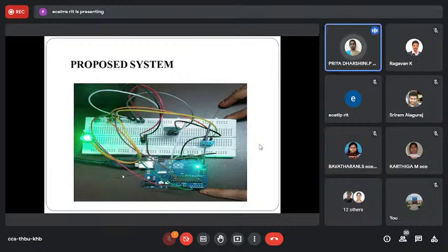The proposed system consists of an Arduino UNO, being an interface for all the sensors: LM35, DHT11 and heart rate sensor, and the HC05 Bluetooth module. The Arduino UNO is a microcontroller based on the ATmega328, and it consists of 6 analog pins from A0 to A5 and 14 digital pins from D0 to D13. This being the interface for all the sensors, we have used 3 sensors.